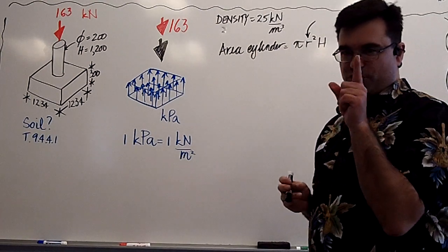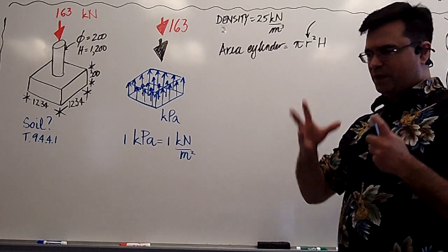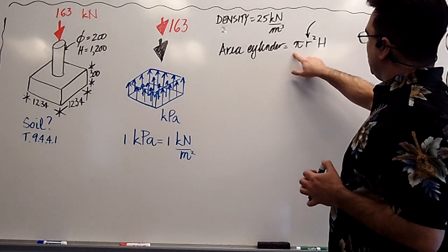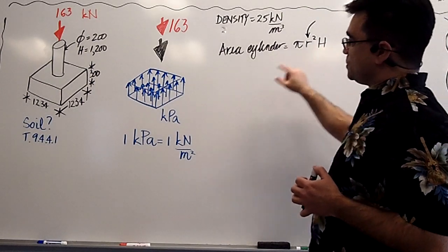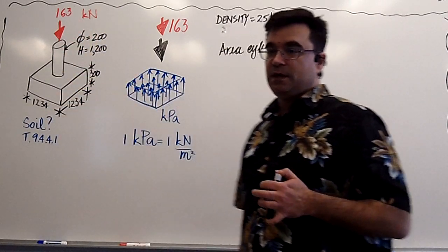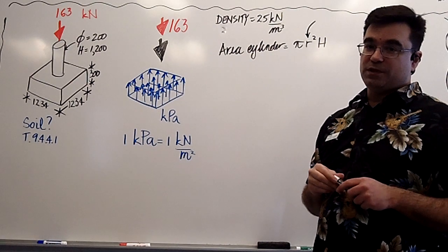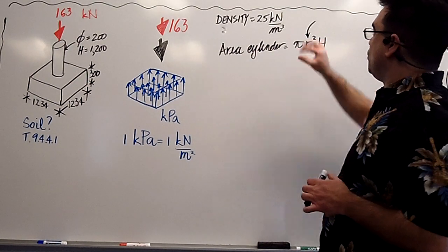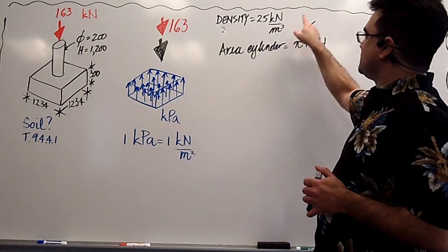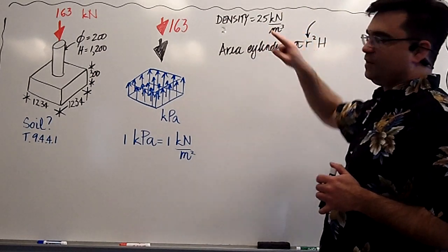Now, I'm going to have some forethought, and I'm going to look forward to what's happening, okay? All of this is in millimeters. This is all given in millimeters. But the density here is in meters cubed, right? So whatever volume we multiply by this has to match whatever units we have here.